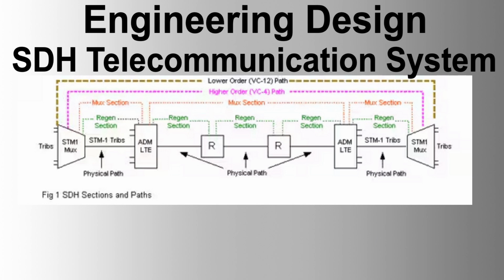Primary multiplexer. Redundant configuration. The primary multiplexer shall be in a redundant configuration capable of demultiplexing a 2.048 Mbps input into individual channels. Protection and interface requirements. The primary multiplexer shall meet specific protection and interface requirements, including 1+1 protection for common control and power supply, and be capable of interfacing with synchronous and plesiochronous networks.